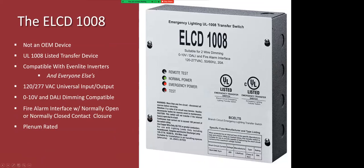I also mentioned about 1008 devices really, really quick, because I know we're running out of time. Again, not an OEM device. This is our own device. It is a 1008 device. It is compatible with 120, 277 voltage. It will do line level dimming. It will do low voltage dimming, 0 to 10, DALI. It has a fire alarm interface. You can use this in your controls design and interface your controls directly with our transfer device.